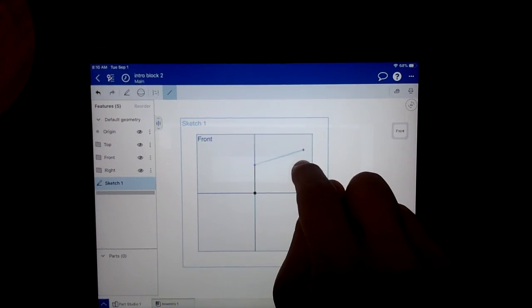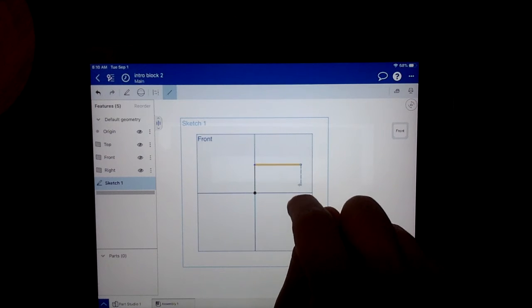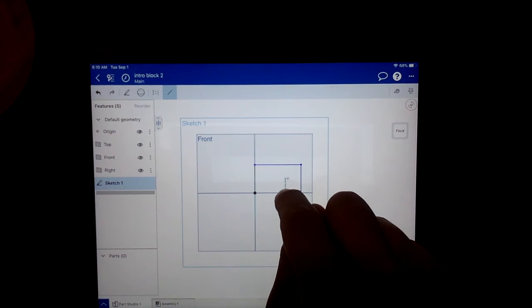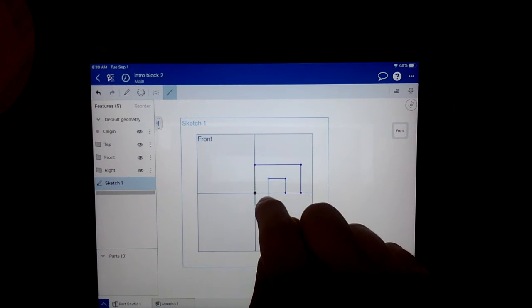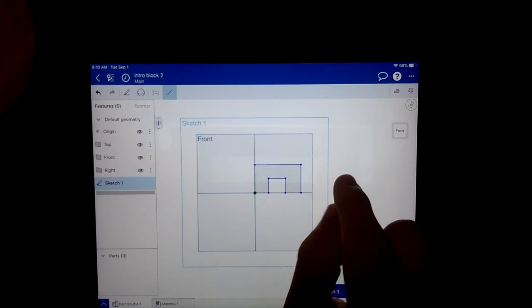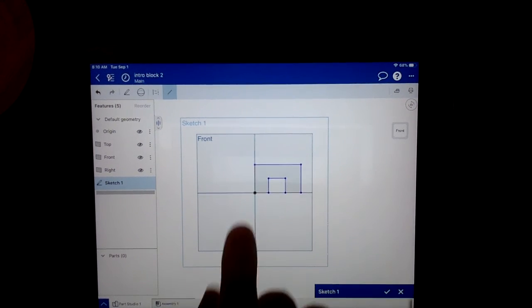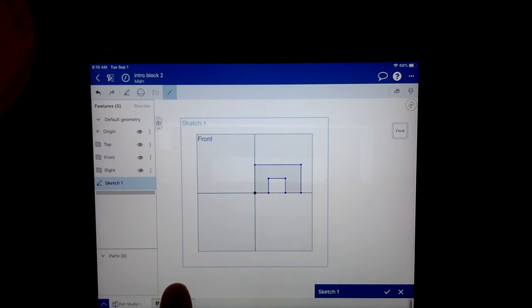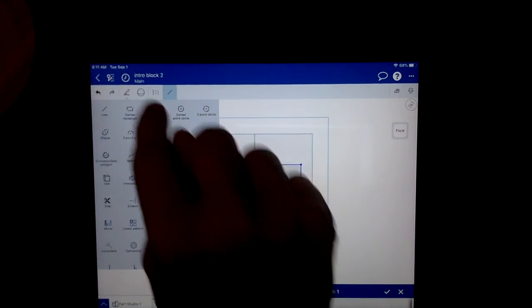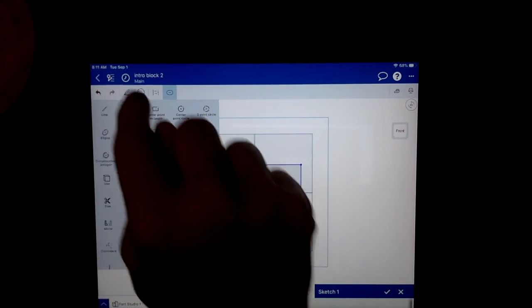What makes this one different is that we actually have to do it in 2 sketches. We can't do it all at once, because if you remember from that initial thumbnail, it has 2 different depths. If something's not perfectly flat, or a uniform height, it takes 2 extrusions or more. So there's my approximate shape.